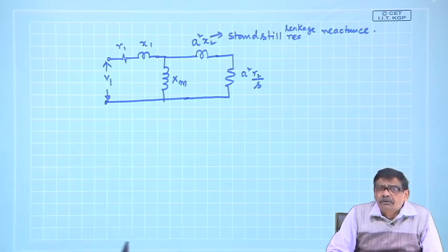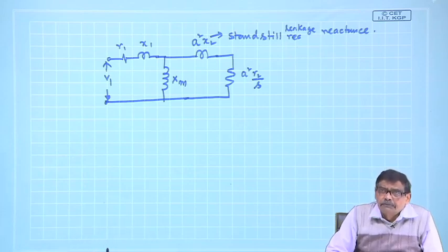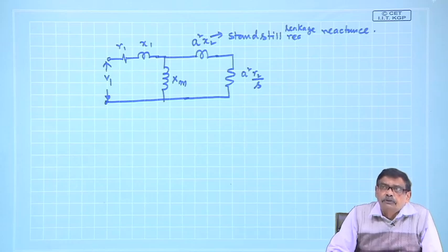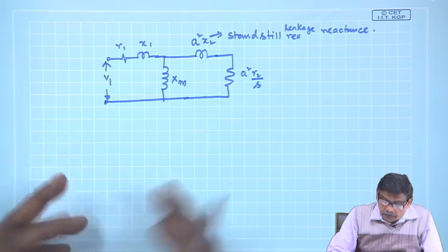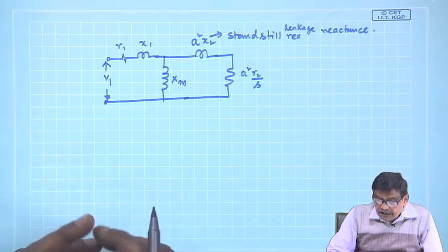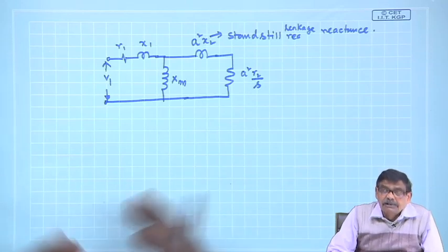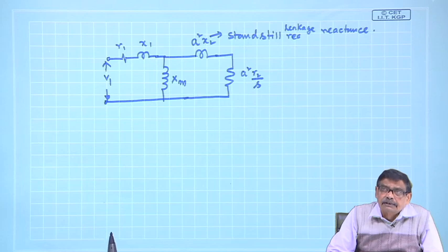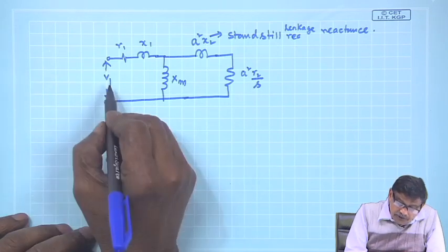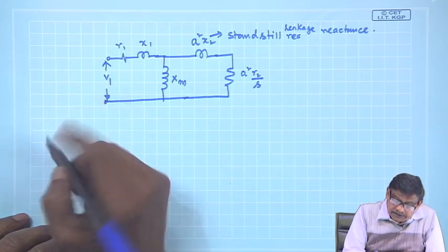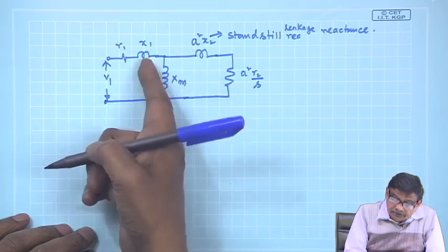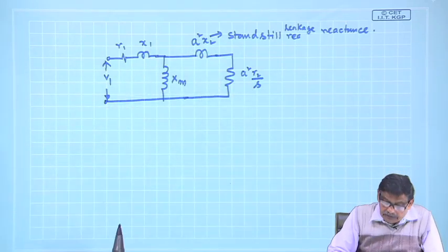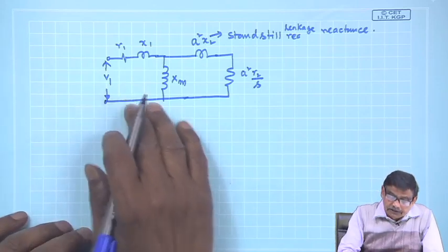We will now adopt a rather softer method to calculate the torque produced by the motor, the current drawn, its power factor, and how, if slip changes, what changes in the circuit and things like that. So, V1 is the per phase voltage, all parameters are per phase, and this equivalent circuit is referred to the stator.